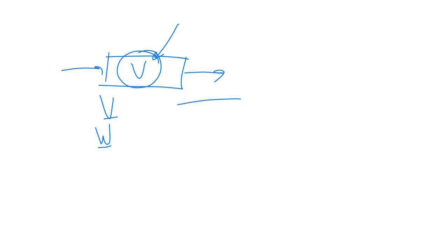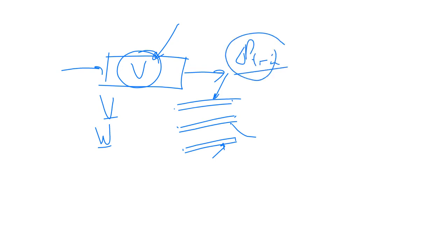You must also specify the layout in the case of a PBR reactor. And how you lay it out, hopefully in the online test, you can see that that affects the pressure drop in your reactor if you've got a gas phase reactor, and the pressure drop affects the performance. So designing a reactor is much more than just specifying a volume or a mass of catalyst. It is also your job to say, how must that thing look? How much area must be available for heat transfer?